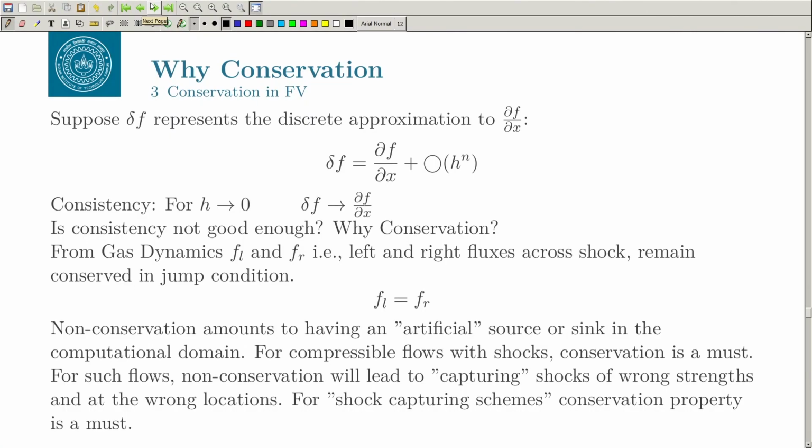Similarly, if you are using some kind of degenerate boundary condition, let us say the wall boundary conditions, again on those boundaries you do not have this conservation being applied in the finite difference case. In the finite volume case we apply it even on the boundaries. So the conservation is guaranteed in finite volume, both the local conservation as well as the global conservation.